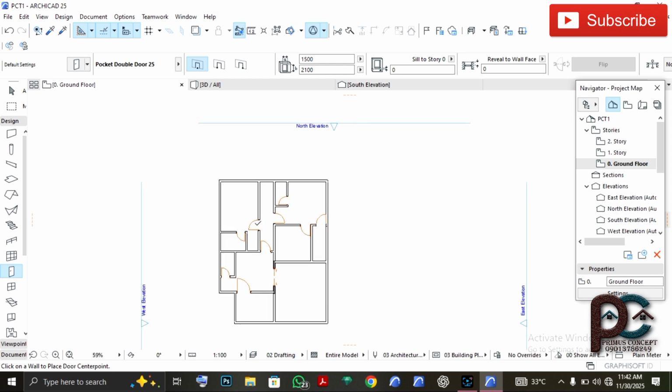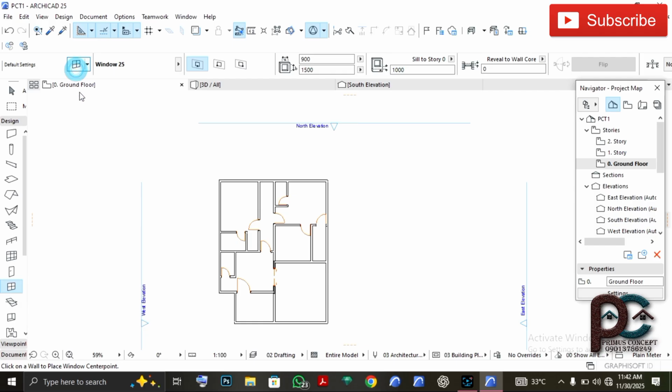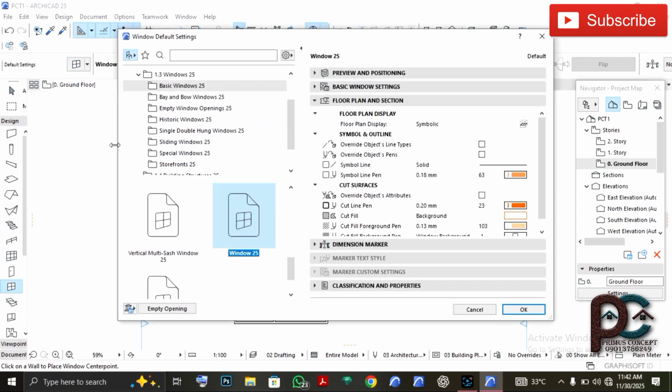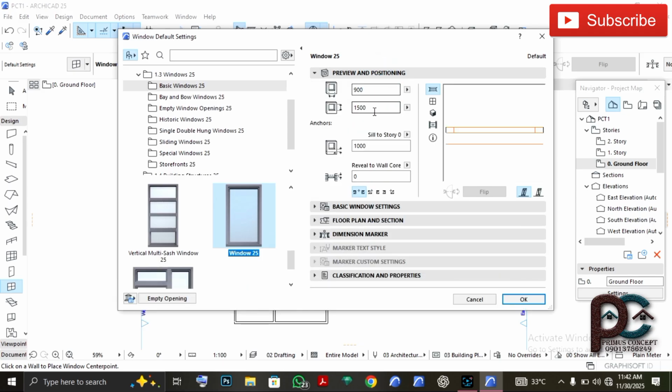And then move to our windows. Go to your window settings. Okay, and for this single window, I'll make the width 600. 1000, because of our height of the window is 1.5, we'll do this 2-story. We'll do 600 to sum everything at 2100.